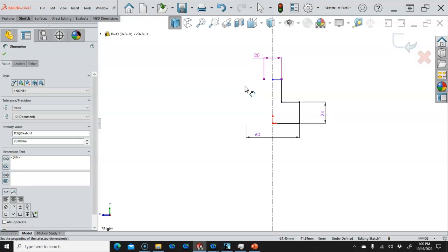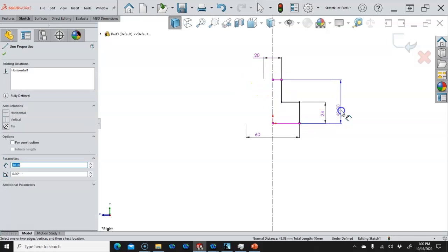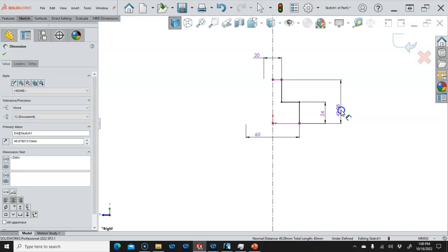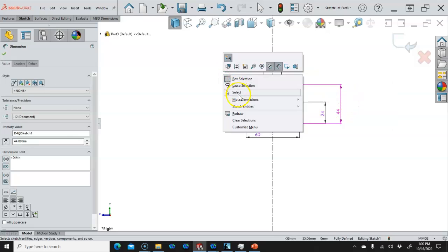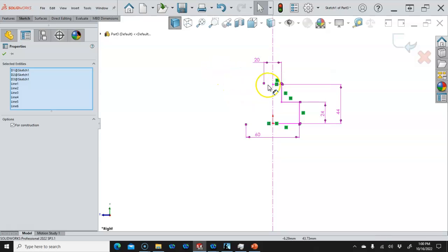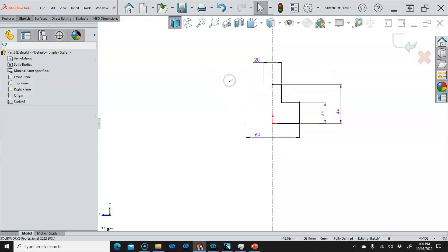And then I can escape. Once will put me back into linear, and twice will clear the tool. Alright, so 44. Select. If we go from right to left, we're going to pick everything, and when I mirror, I will get the entire object.